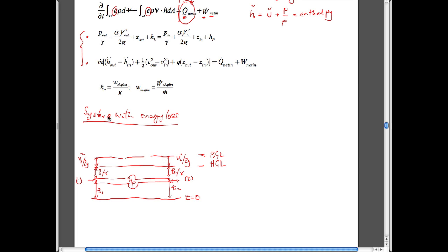And so we can quite simply think of the other terms that we would put into a system as being a magnitude of pump head, which we'll call H sub P, which gets us up to this point, which raises, if you like, the energy in the system. And if everything was fine and our system was still inviscid, then this horizontal line would be our revised energy grade line, number 2 if you like, because we're not losing any energy in the system.